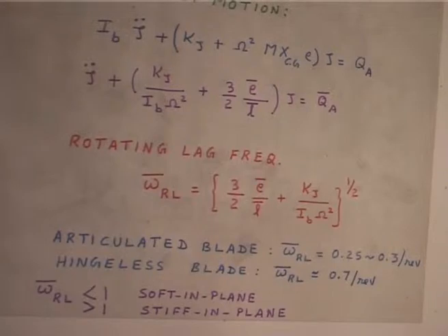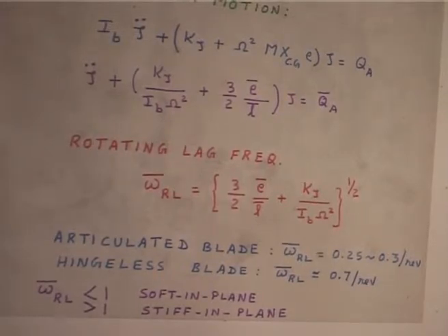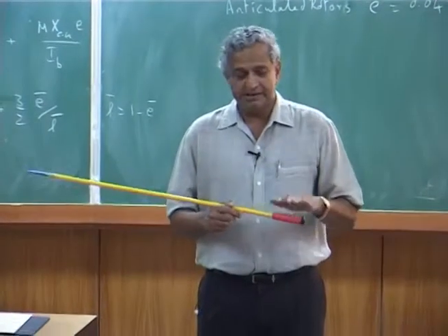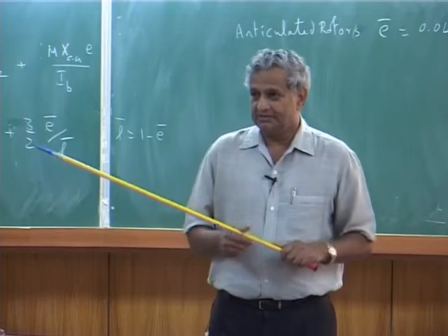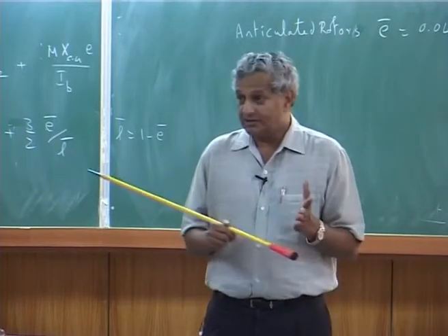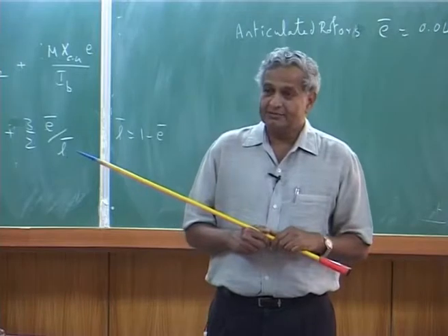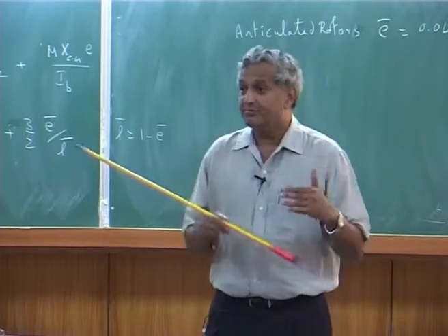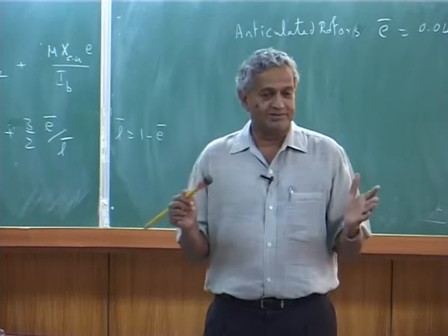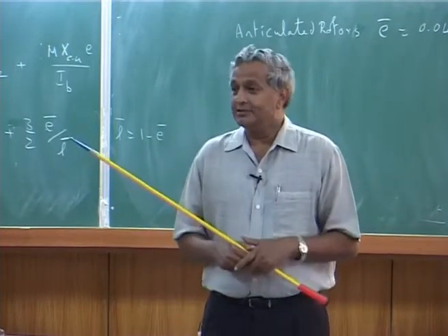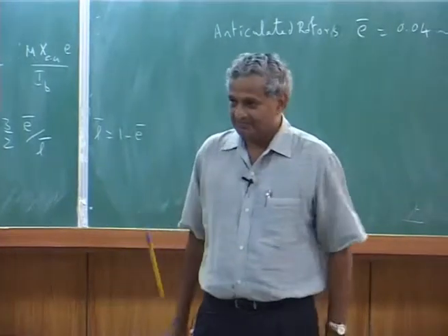I do not know who all came that day for that presentation. That is a ground resonance, in which blade lead lag motion coupled with the body motion, and then that will be very catastrophic actually, and you have to avoid that. But the loads are less, vibratory loads. So, the question is, what kind of rotor system you will choose for your helicopter.